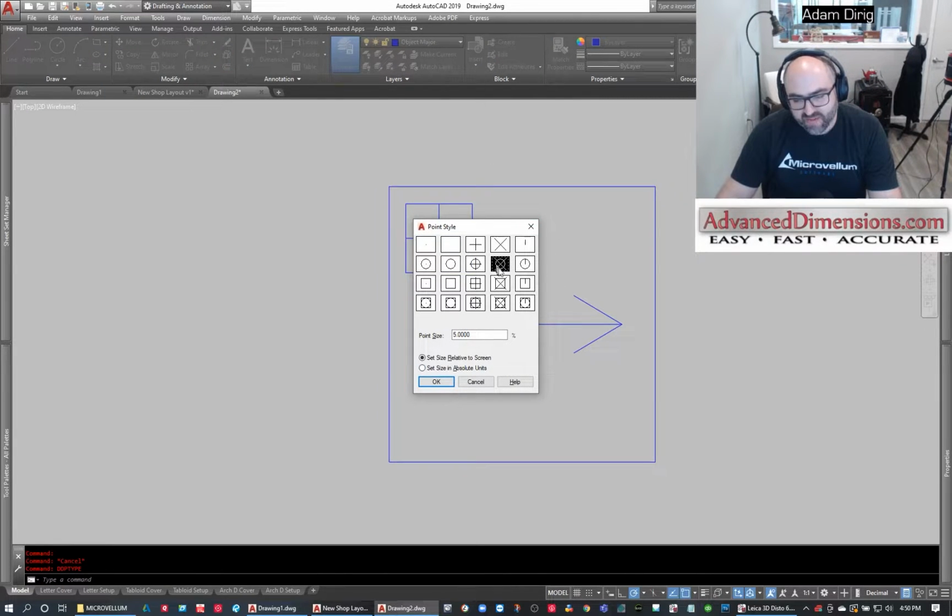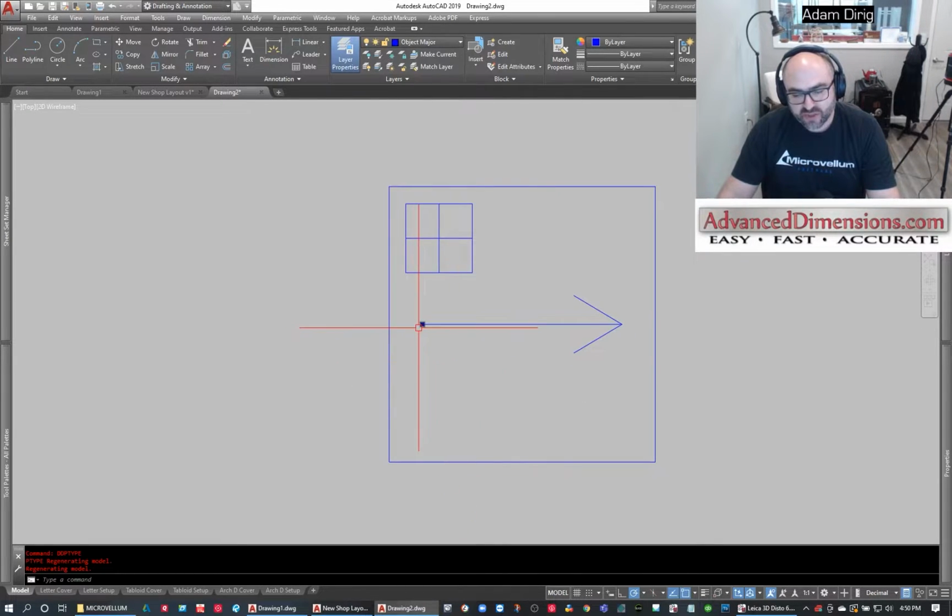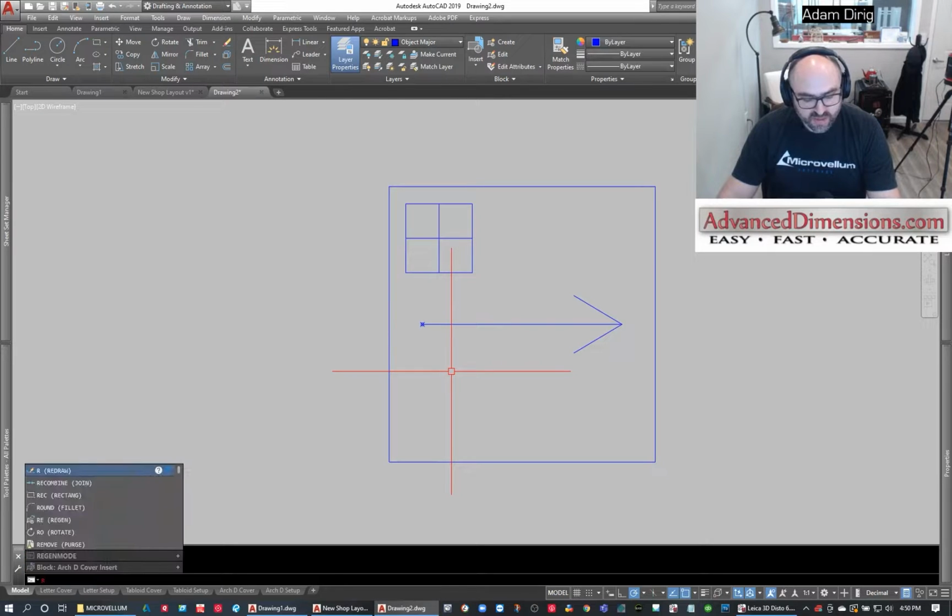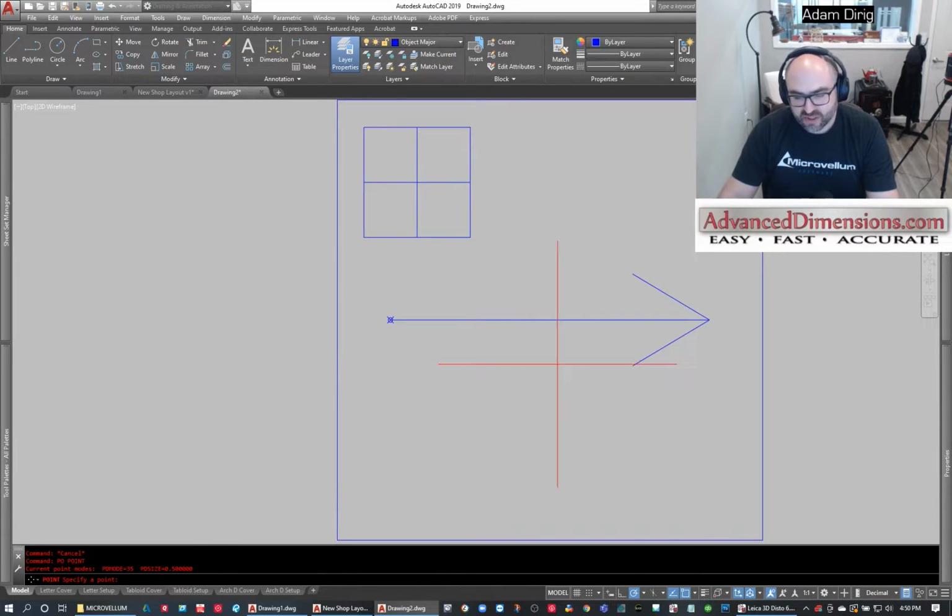So right now I have this crisscross, which is good. I actually want to make it so that this point is coming in at a 0.25 because they get too big sometimes, and I want to make it an absolute number instead of a relative one. Actually, let's do 0.5. Because when you zoom in and zoom out of the relative, it's going to change the size of that. So here's my point. Now I'm just going to start adding some points to the mix.